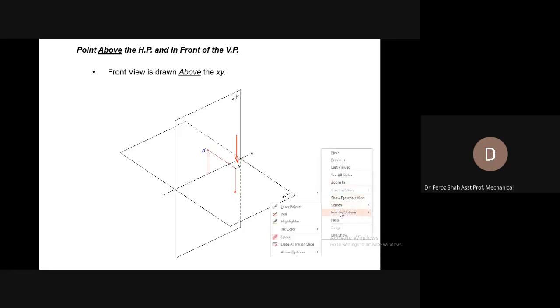That is why we rotate it, in order to bring it in alignment with the front view. That would make the two views to be efficiently drawn, as most of the common dimensions would be only drawn once, and this would eliminate the redundancy in your drawing sheet and make it more efficient.